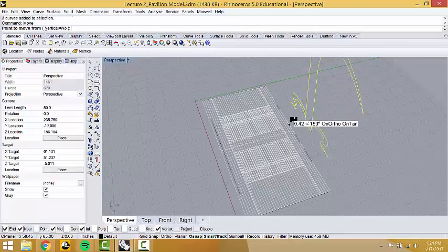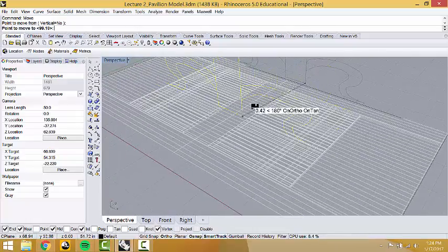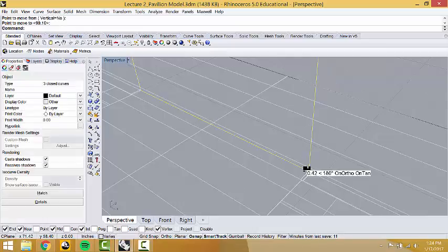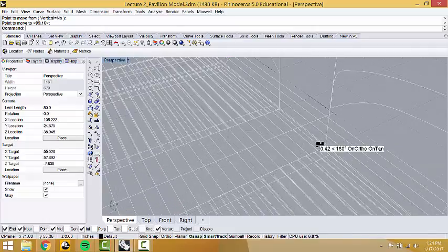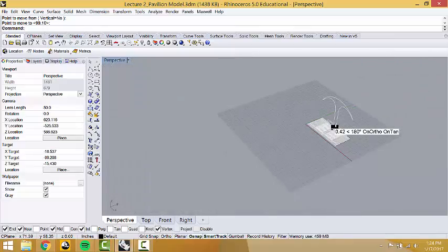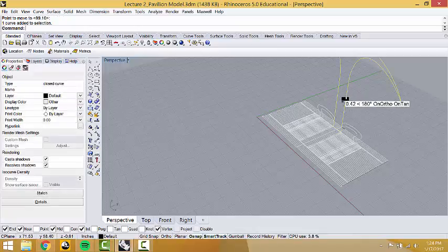You can group things later in Rhino, but you can't use the lines individually, so I often will group them later. So I have used my O-snap to click in perspective some sort of alignment of this side elevation to the plan. That looks pretty good. Now I can grab this guy.